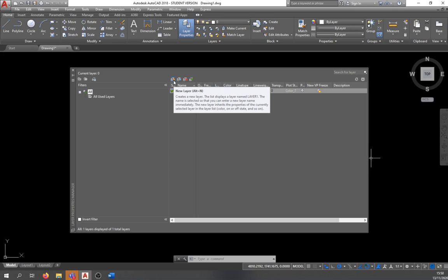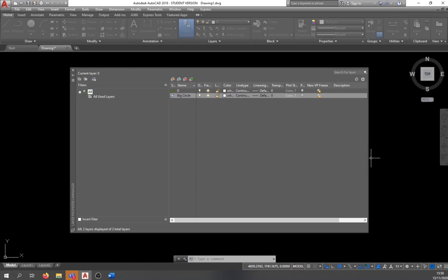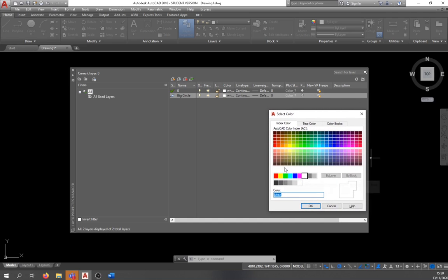We're going to start a new layer first of all. Again, this follows a little exercise in the notes. We're going to draw a little clock. So we're going to click the first layer. By default it comes up with layer 1, and every layer you add is going to be layer 2, layer 3, for example. I'm just going to rename this one Big Circle, and I am going to give it a color green. These are all the index colors here. Just for these exercises you can use the default ones over this side. So I'm going to give it a green color. Click OK.